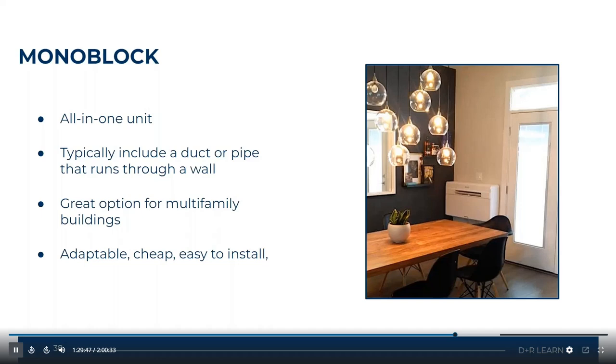Yeah, Lester, they're agreeing and referencing that an alternate source is needed. Absolutely. My recommendation for mini split systems is you could do a natural draft or natural type of ventilation or introduction of fresh air. My recommendation is if you don't have that type of airflow in that environment, by opening a window or a door, make it mechanical.